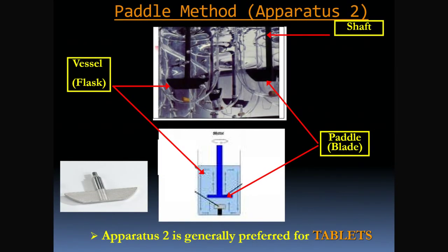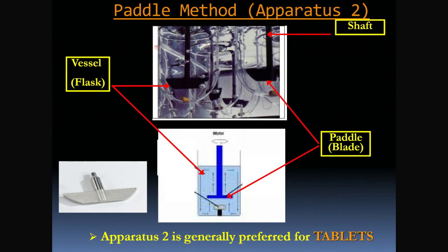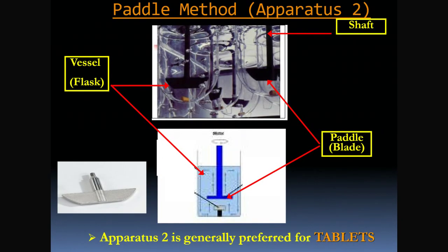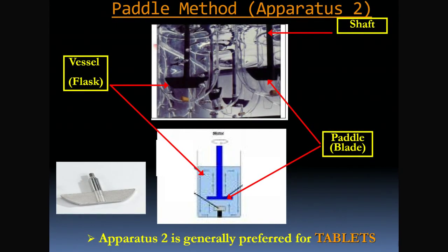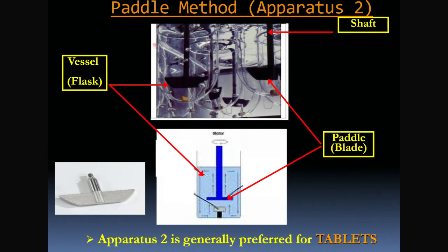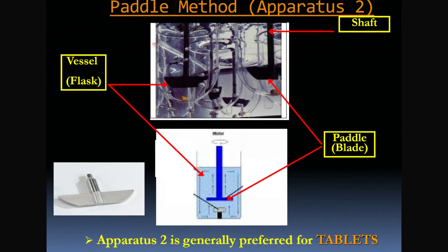Evaluate the physics of this setup. How might the shear stress exerted by the fluid change if the tablet is positioned off-center versus directly under the paddle's axis of rotation? Maintaining a standardized distance between the paddle and the vessel bottom is mandatory because this gap directly influences the local Reynolds number, ensuring that mass transfer kinetics remain reproducible across every trial.